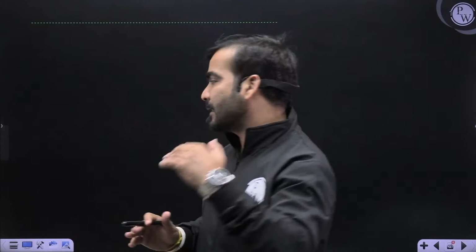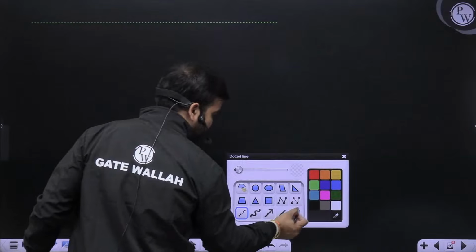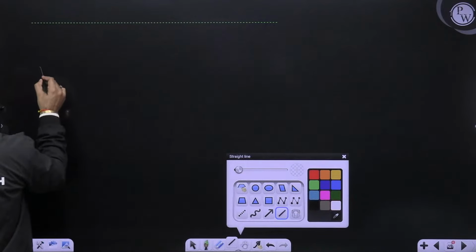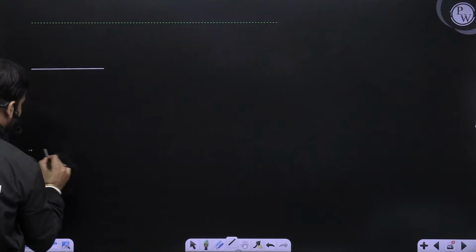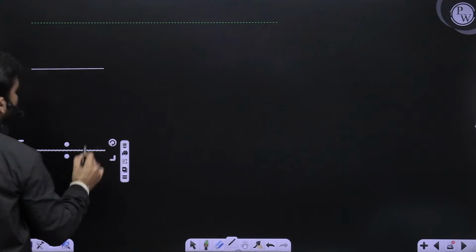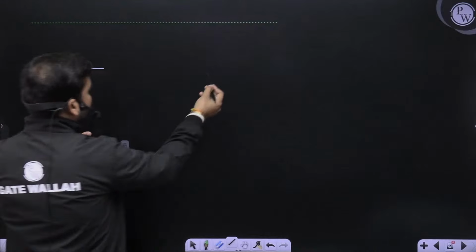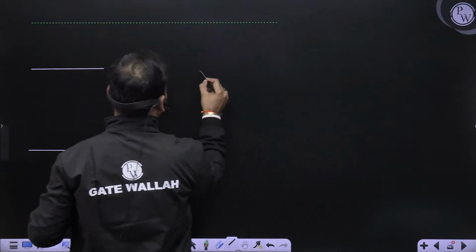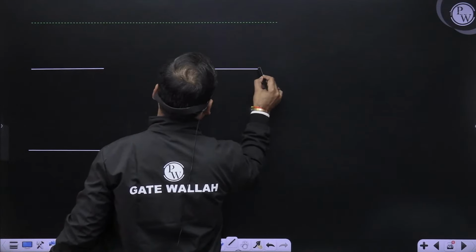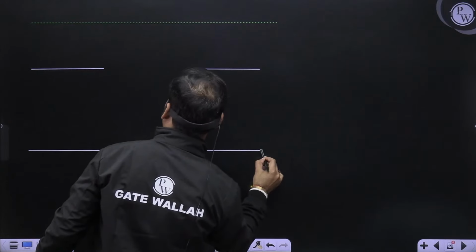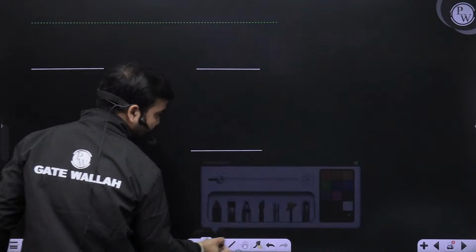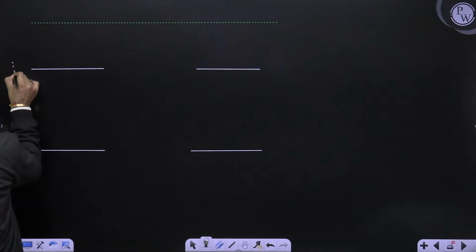Meaning is that the Fermi level is coinciding with the conduction band edge. Suppose here it is a gate material, which has the conduction band, and here the valence band. If this is a silicon gate material, the substrate is also silicon. So here will be your conduction band, and here will be your valence band. Very similar. Okay, so this is your conduction band in the oxide.